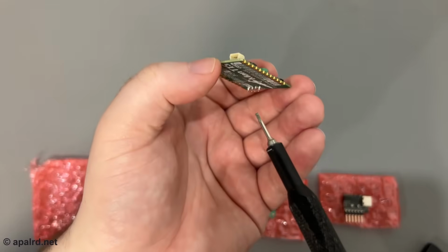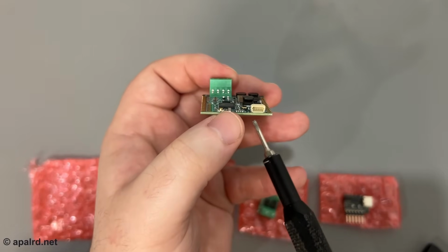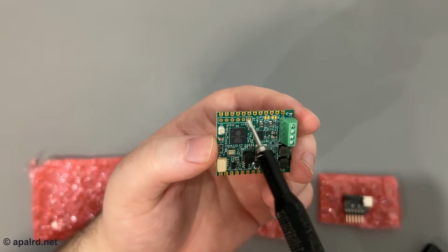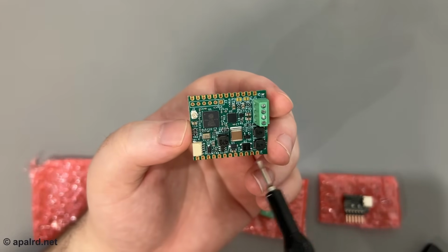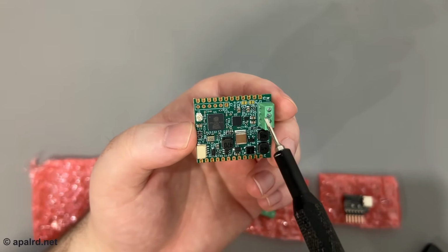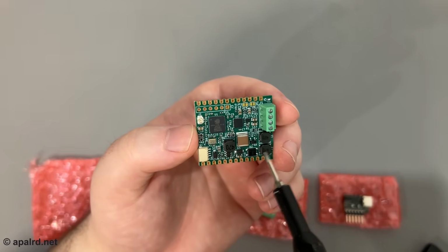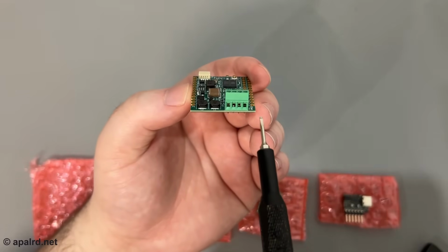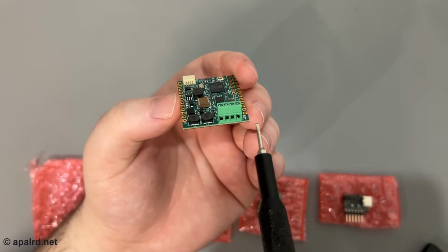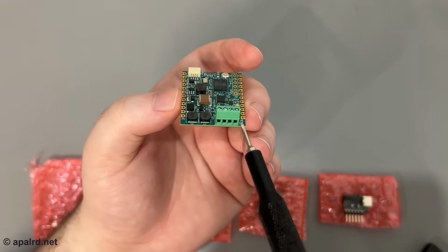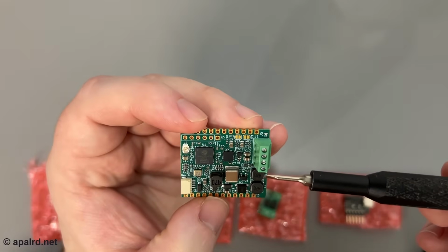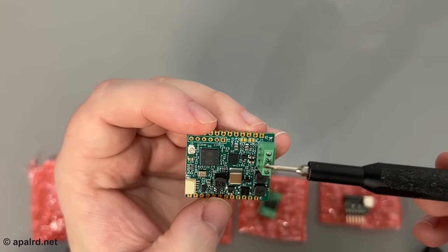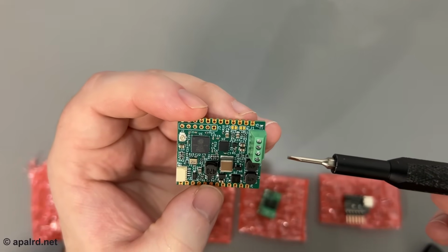He's got what's called a quick header here if you want some I2C stuff. And all the other pins are brought out to the castellated pins or the programming header. It's got a power supply to take 48 volts from the bus to power itself. The bus itself is this little screw terminal connector here. There isn't exactly a standard connector outside of automotive connectors, so he just got this, and there's just two copies of the same bus. So it's a 2-wire bus. You can daisy chain it through by using the extra screw terminals.